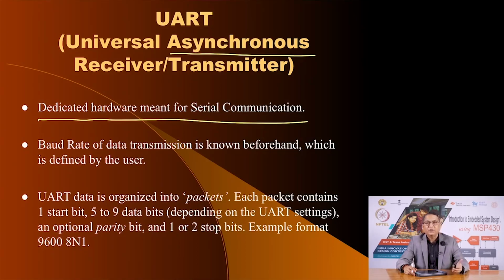Therefore some other method of knowing when one bit ends and the next bit starts has to be decided, and one method of doing that is to agree upon a certain time for which each bit will last, and the resultant rate is called bit rate or baud rate. The user has to define this before any communication can happen. And of course, both the devices must agree on that bit rate or baud rate.